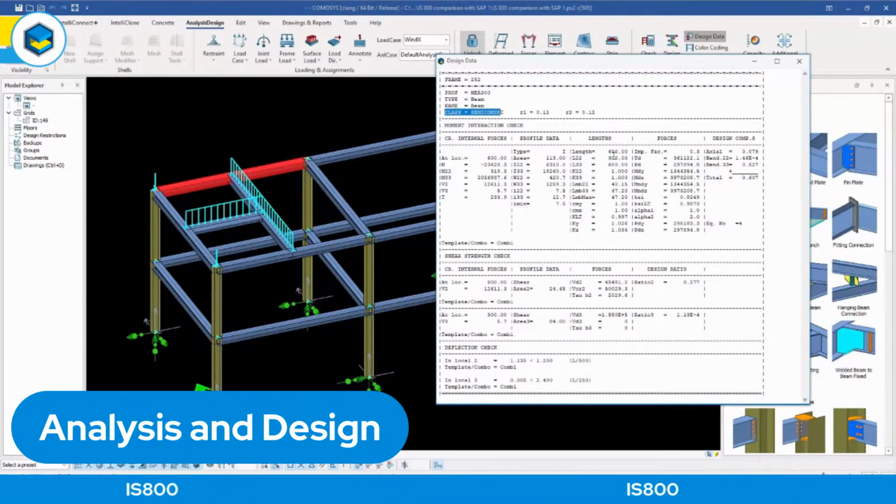Similarly, the section properties are given over here. The other geometric properties of the section are given over here. This is where the meat of the Indian code is. So you will see the TD value, which is related to the Indian standards. This will all, of course, be given in these units, which you have at the bottom right of the screen. The PD value, the MDY, MDZ, MNDY, all the engineers who are designing according to the Indian standards will know what I'm talking about. MNDZ, KSI, KSI LT, the alpha 1, the alpha 2 values, these are all related to the buckling coefficients. PDY, PDZ, all these values are then used in the basic axial, bending 2-2 and bending 3-3 components of the total design stress.